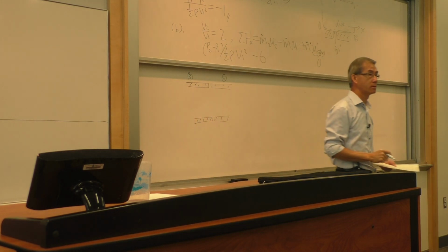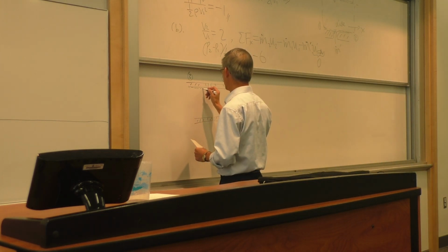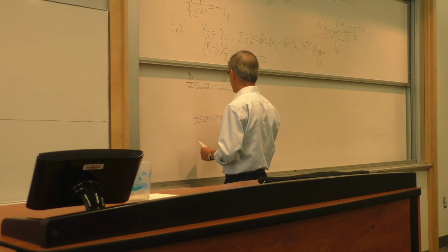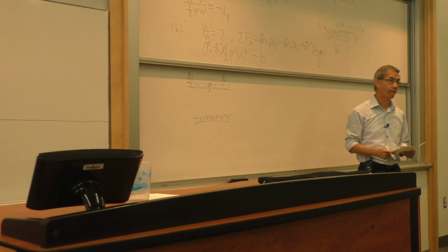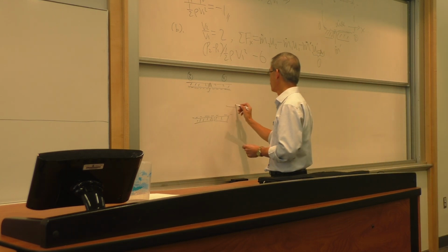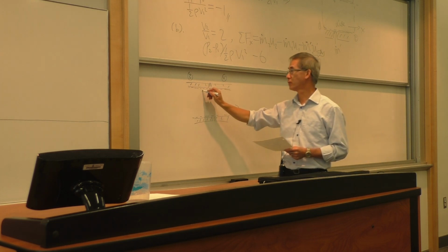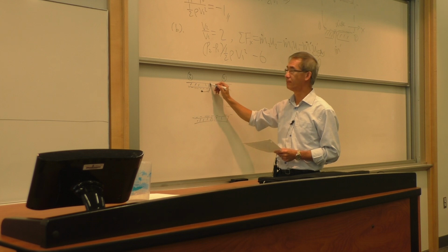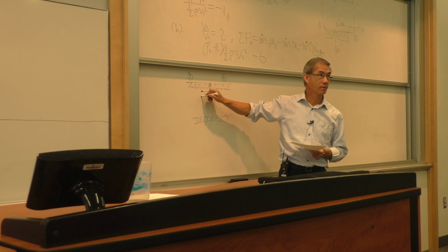So at first sight, the temptation is to reuse the momentum equation, reverse of what we did in part B. The only problem is, when you rewrite the momentum equation from 3 to 4, as the fluid now leaves this dashed line, the control surface, does it have any x momentum associated with it?